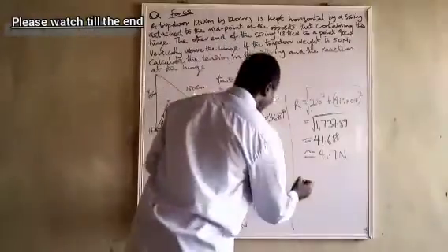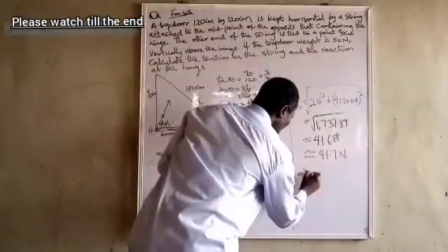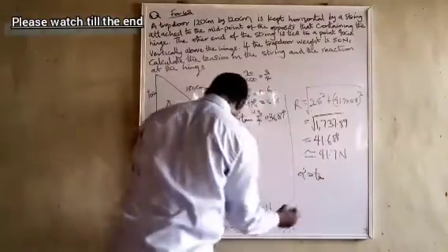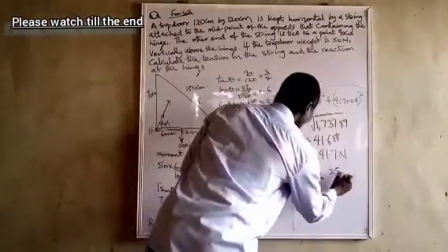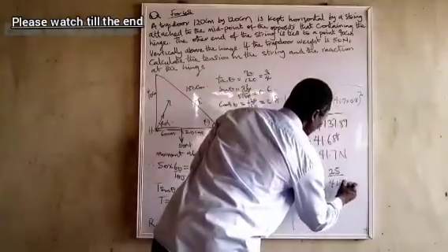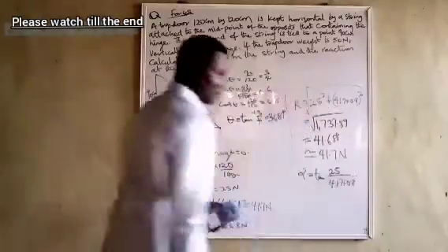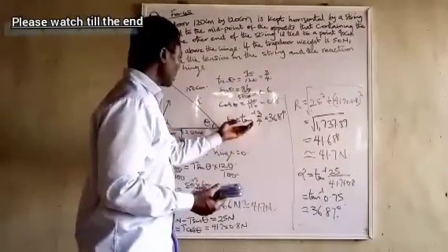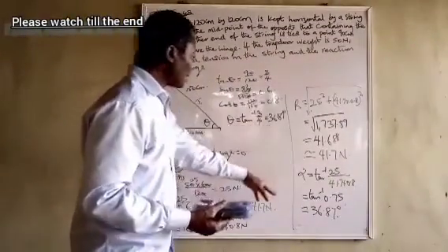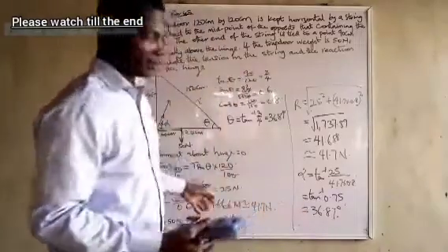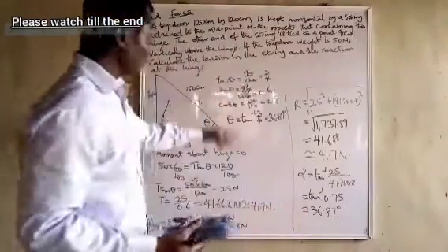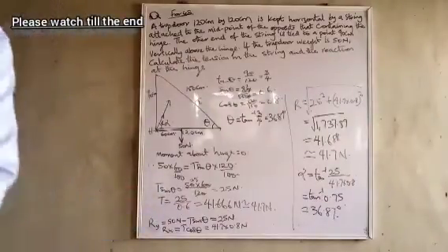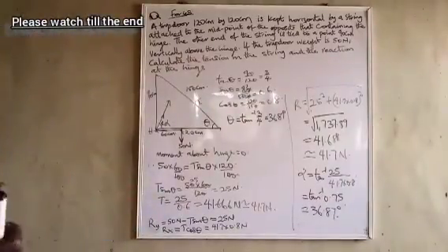You can find the value for R. Alpha will be equal to arctan of 25 over 41.7 times 0.8. So you can see this is the direction for this, and at the same time they are equal. The direction for this one also is 36.87. You can also do it by drawing the triangle and using Lami's theorem or whatever theorem you want to use.